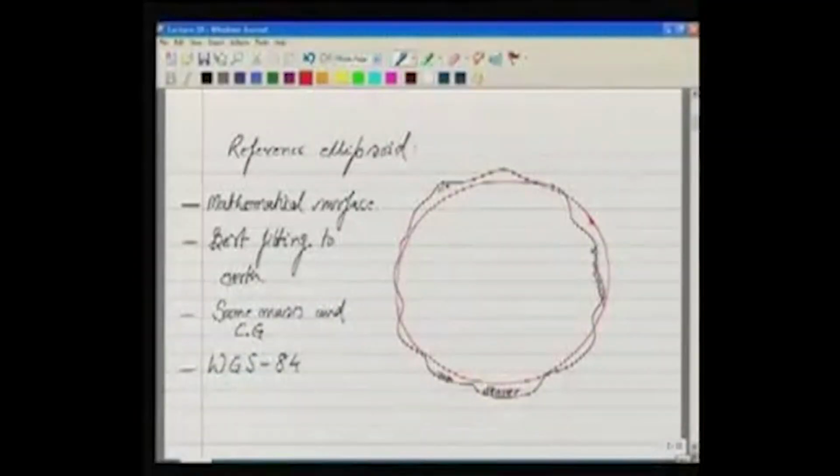Unlike in surveying, because in the case of engineering surveying, so far we just discussed somewhere a geodetic survey, but mostly in engineering surveys we can consider our coordinate system to be a local coordinate system, unless the project is very large, and in that local coordinate system we can carry out all our measurements, all our setting out. Over here, in the case of the GPS, for coordinate system we would like to define a reference ellipsoid.